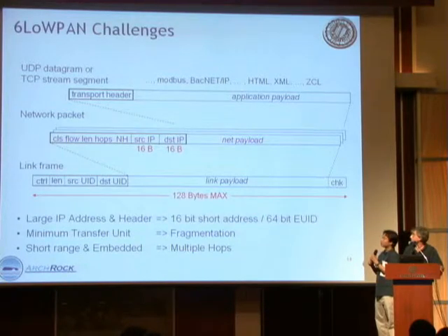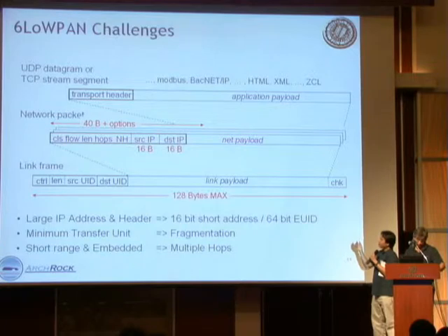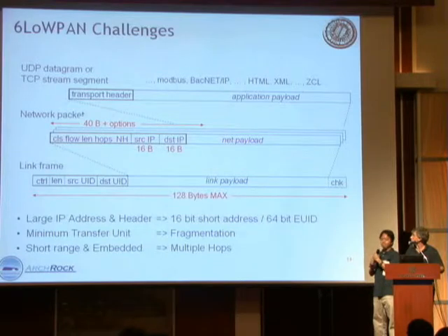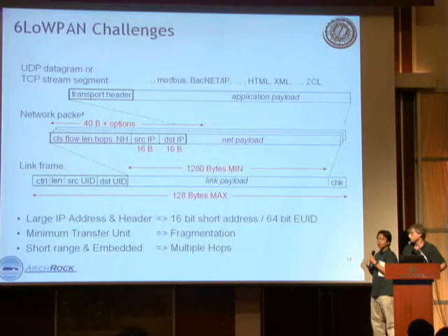But the 15.4 packet is only 128 bytes, and the header for an IP packet is at least 40 bytes. In fact, the minimum size is supposed to be 1280 and we only have 128.